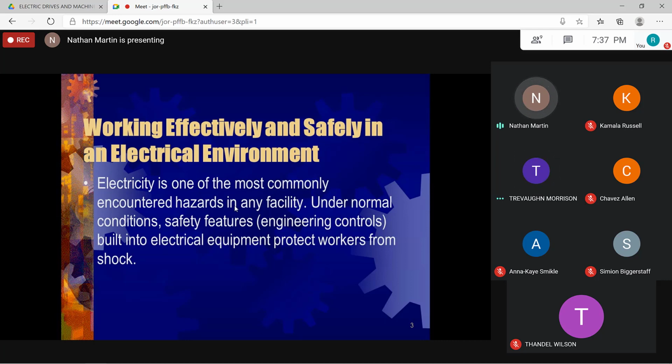Sparking. When you try to connect a live circuit, what you have is sparking when it's on load. Because remember, the load is something that will be pulling current, right? And yes, you are going to be pulling current once the two wires get close enough and start to touch. The instant they start to touch, you are going to have a produced arc. And the danger of having an arc, if it's too high, is what? Electric burn. Flash arc burn, they call it, right? Very dangerous. So the first step is to de-energize the main breaker, right?